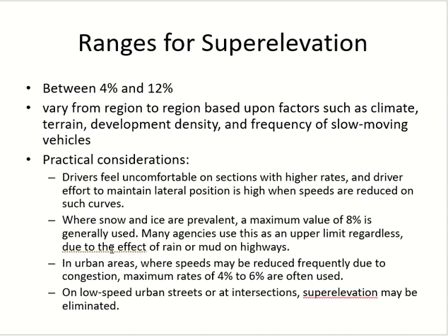When you are on a curve and you see the superelevation is very high, you try to avoid the side, because you feel if you go to the side of the road, you are going to the highest point of the curve. So you try to go in the other lane, you try to avoid it. And obviously if you cannot do it, then you go slower. So comfort of the driver should be there. Snow, ice, anything which makes the pavement wet should be taken into consideration.